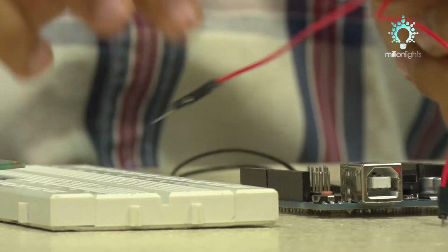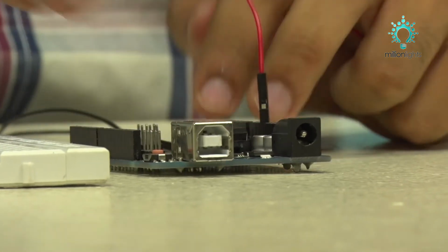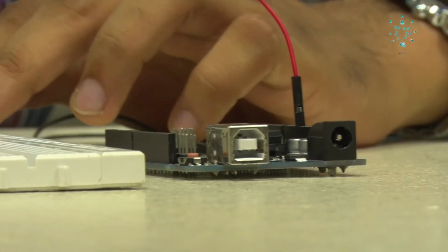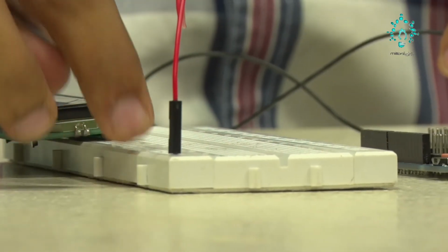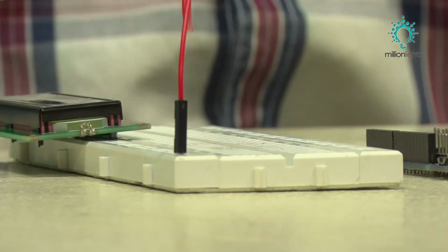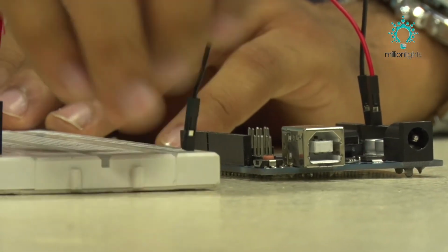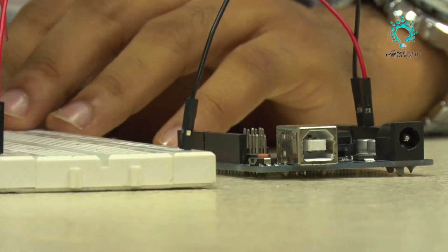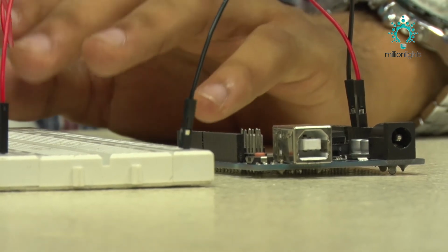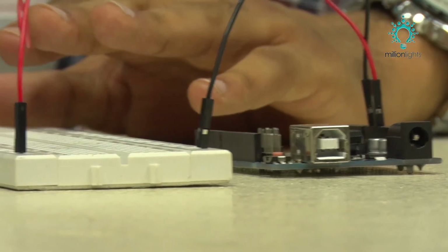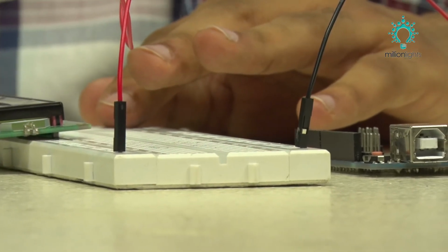First I'll connect VCC on the right hand side. So this right hand side rail is completely VCC, 5 sections: 1, 2, 3, 4, 5. These 5 sections are VCC. Then I'll connect ground on the left hand side, again 1, 2, 3, 4, 5. These 5 sections are ground. Anywhere you want to provide 5 volts, you connect to this, and anywhere you want to connect ground, you connect to that. So we have created VCC and ground points in our circuit.